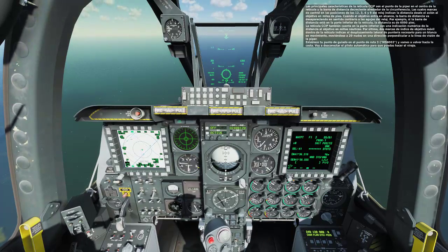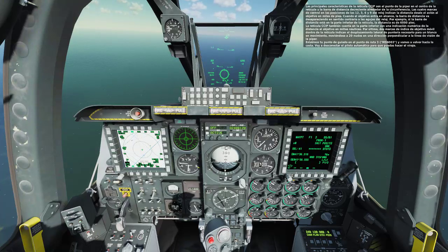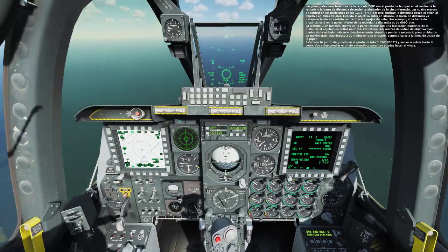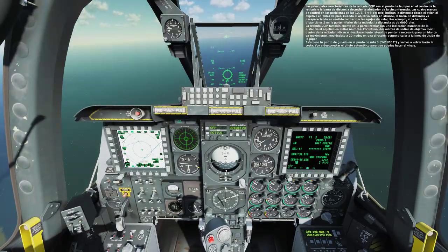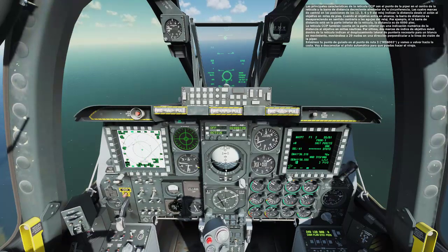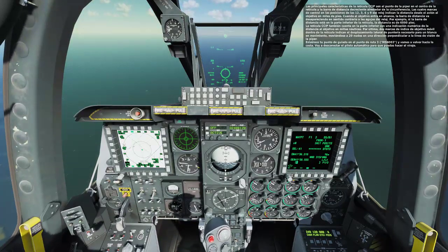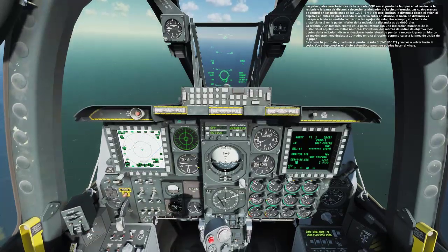The CCIP gun reticle also features a numerical indication of the slant range to target in nautical miles below the reticle. Finally, two moving target index marks inside the reticle indicate the aiming lead required for a moving target traveling at 20 knots in a perpendicular direction to the pipper line of sight. These are currently latched to the outside limit of the reticle at 3 and 9 o'clock positions due to the high slant range. Set your steer point for waypoint 3 and let's head back inland.